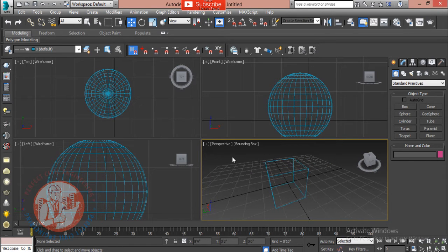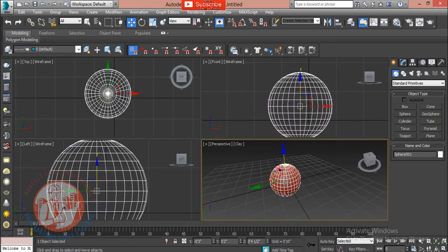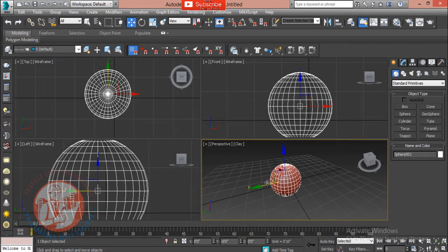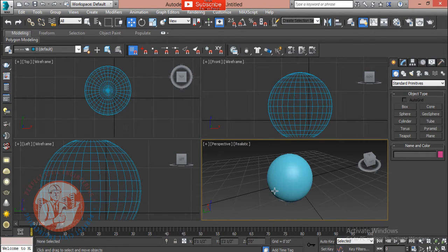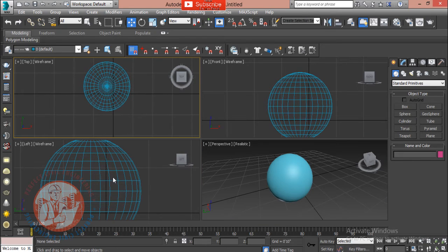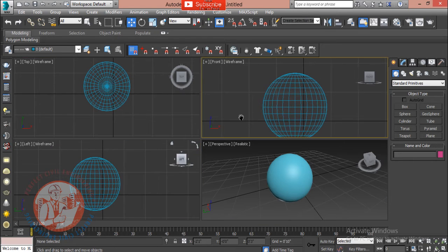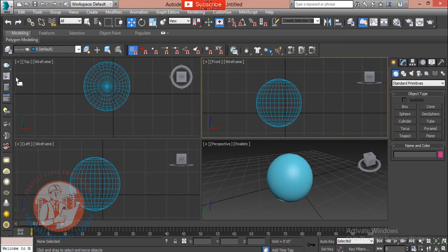The realistic shading method uses any applied textures and high-quality lighting and shadows. The shaded method is similar, but it uses a quick shading method called form shading. The consistent color method displays the entire object using a single color without any shading. The simplest rendering setting that represents the shape of the object is wireframe. It gives a good representation of the object while redrawing very quickly.